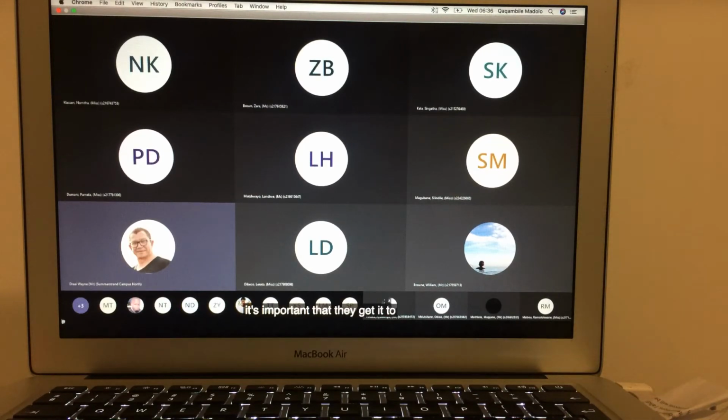Exposing the piles for inspection. It's important that they get inspected to ensure that everything was done correctly in the pile. We normally would clear the top of the pile in order to see what the density of the concrete is, whether there would be honeycomb in that or not. Because honeycomb, what does honeycomb refer to? Honeycomb refers to weakness. So it's water that has disappeared from there, and it does not form the bond. So it's important that we have that in there as well.